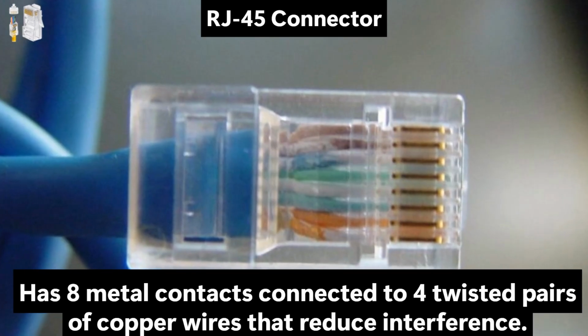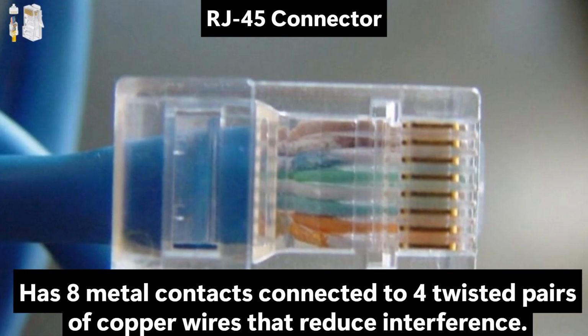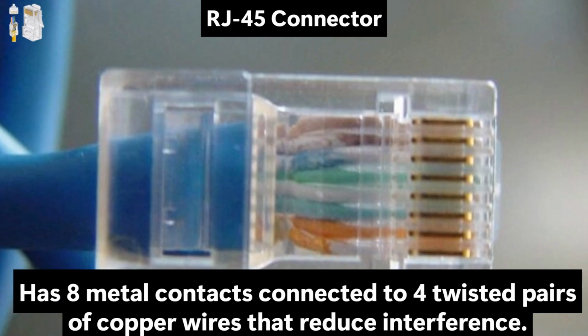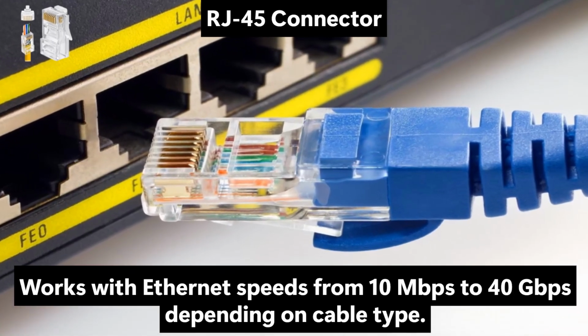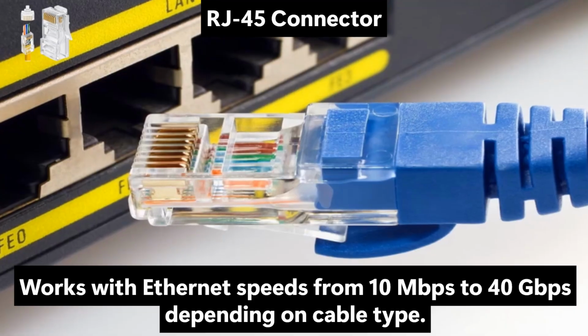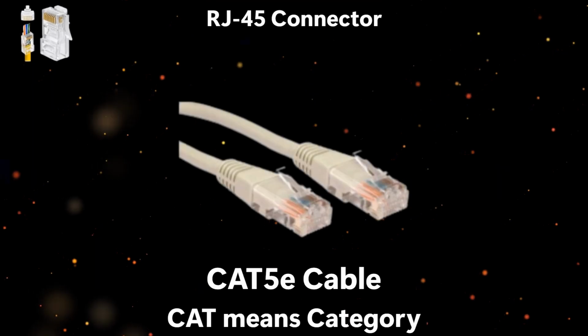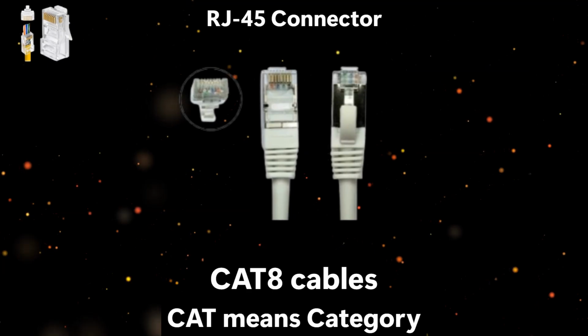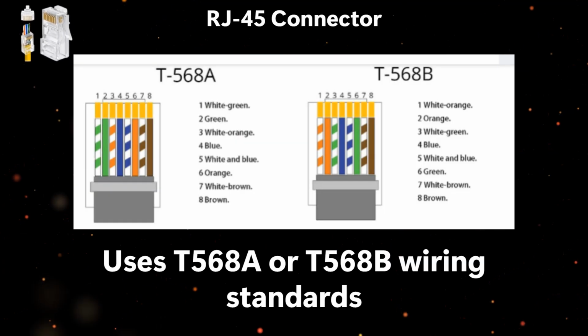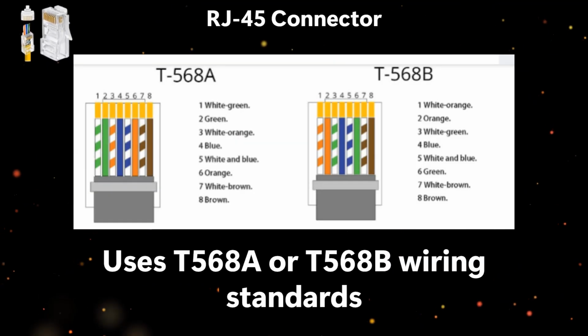Has 8 metal contacts connected to 4 twisted pairs of copper wires that reduce interference. Works with Ethernet speeds from 10 megabits per second to 40 gigabits per second depending on cable type. Compatible with Cat5, Cat5e, Cat6, Cat6a, Cat7, and Cat8 cables. Uses T568A or T568B wiring standards.